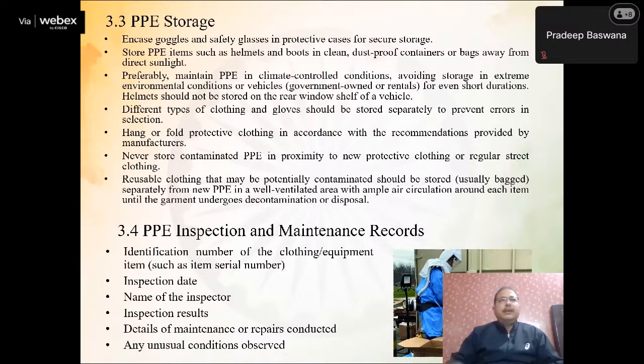You are very knowledgeable, you can directly say go and use SCBA. No, it's not like that. Is the SCBA properly decontaminated? Has it been kept in a safe environment? What inspection and maintenance is required? A country like India doesn't have n number of PPEs that we can use every time, and it is not very evident that each and every time we have to face the situation. So we have to focus upon these SOPs so that we can protect ourselves also.